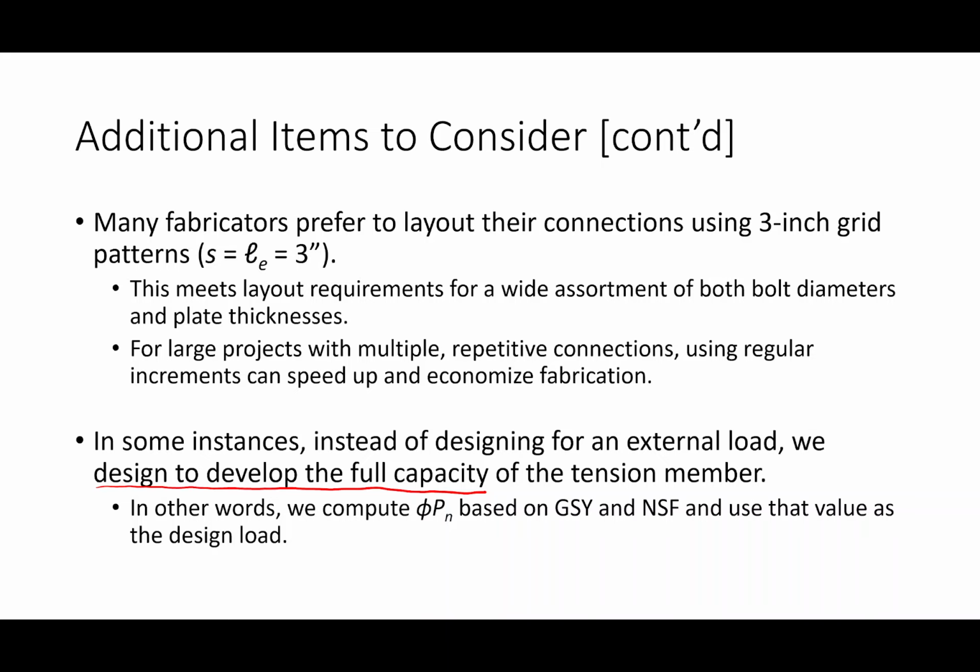The logic behind doing that is that it doesn't really matter what force is on the member, the connection is going to be able to hold it, because the connection is going to be stronger than the member, just barely stronger than the member. Does that make sense?